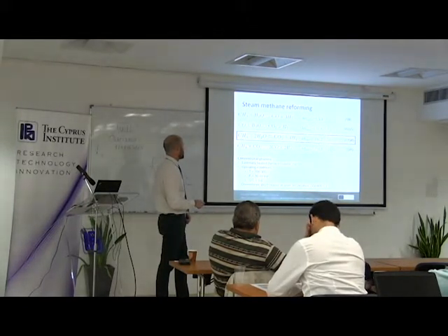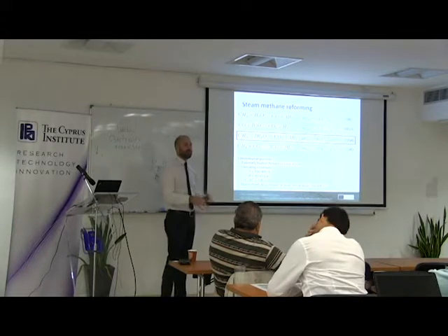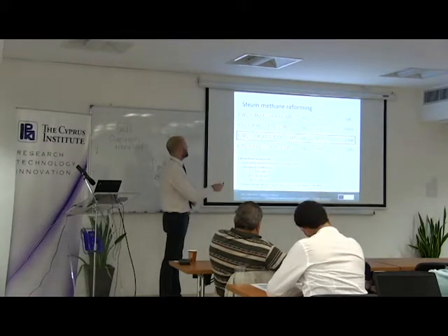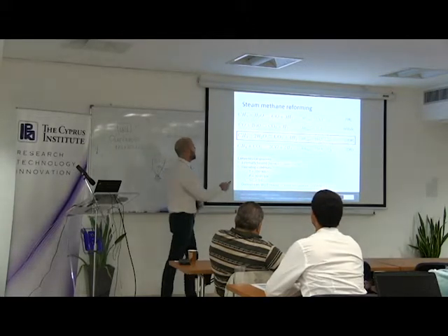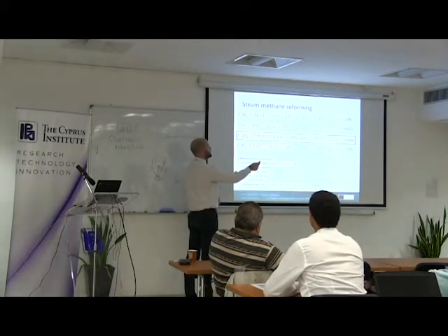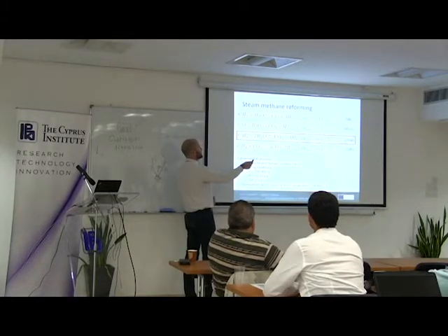The pressure is between 10 and 40 bars, and the temperature, as you see, is very high. Usually it requires 2 reactors because you have a first step at high temperature, in which you carry out this reaction and produce the so-called syngas, a mixture of CO, carbon monoxide, and hydrogen. And then, since your objective is obtaining hydrogen, you want to further convert CO into hydrogen, so you carry out the Water-Gas-Shift reaction.